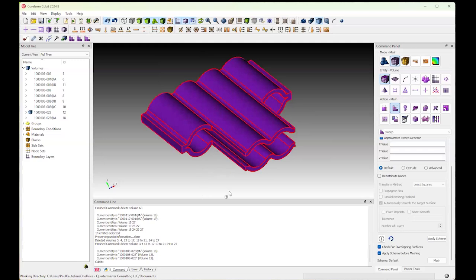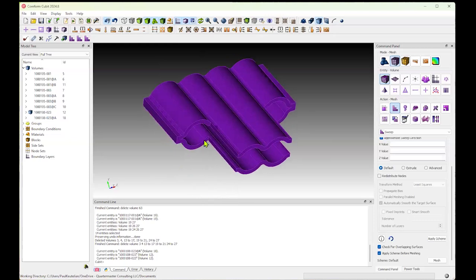One is to try and get to hex meshing everything as much as possible. Hex meshes are nice because the matrix is a little bit stiffer, the solutions are a little bit more stable. They conform to geometry a little bit better, and it's fewer nodes. It's computationally easier because you have so many fewer nodes and connections for each of those versus like TET meshes.